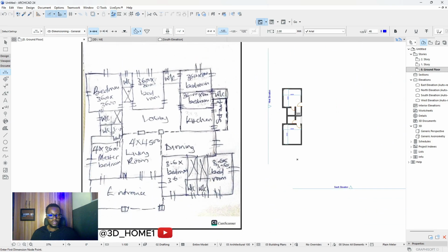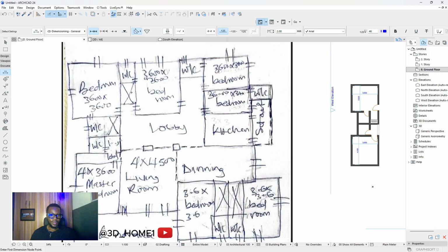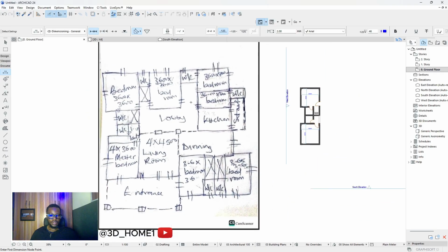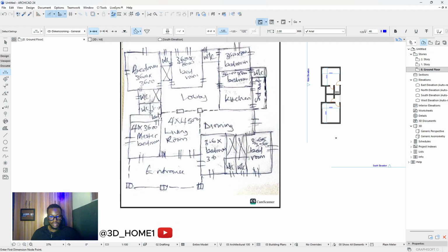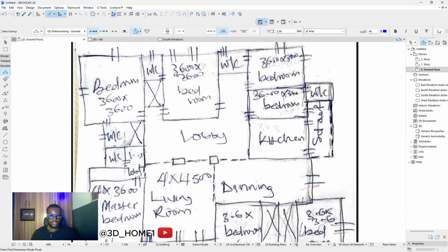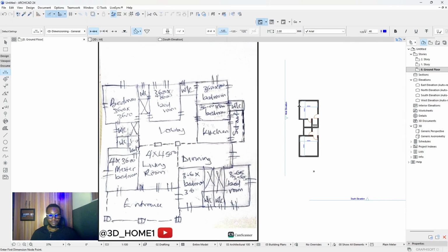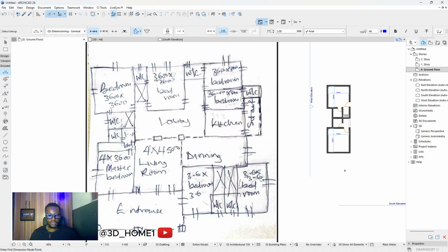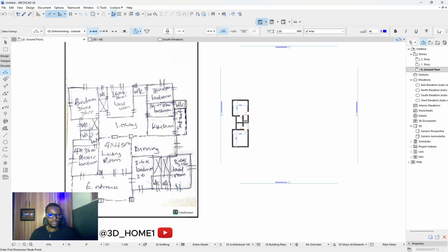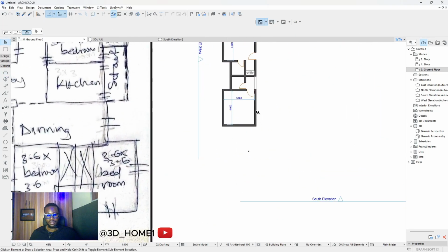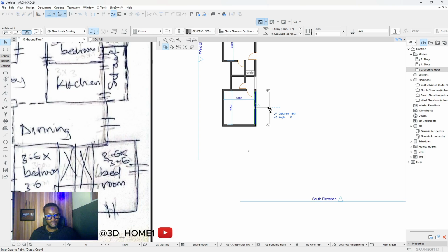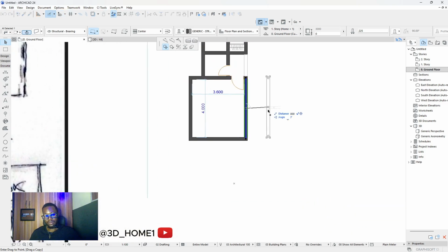The next thing is going to be this room. So I believe this line aligns with this down part. Okay, so let's first of all get this one, which is 1.5. Mind you, we're making use of the same measurement. Since there's no measurement in this one, we can get this measurement, then align it to get this measurement. Anything at this level, we use it for this toilet. Okay, so we'll go with 4 meter from here to here. Go with 4,000.